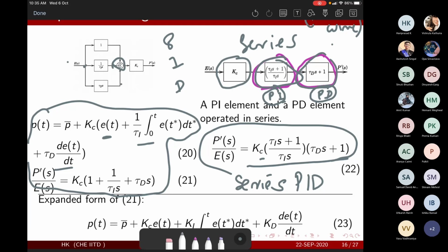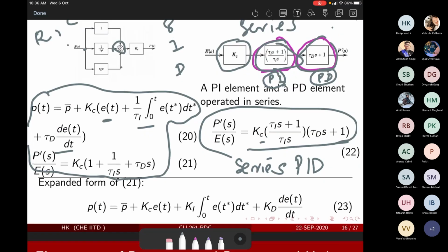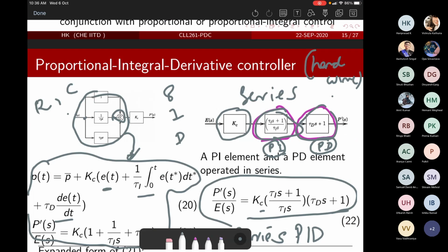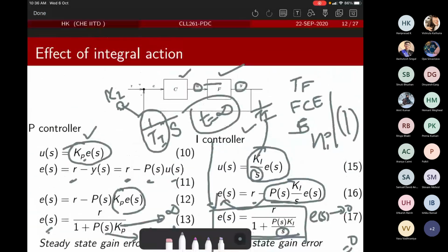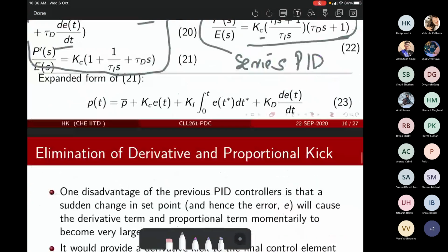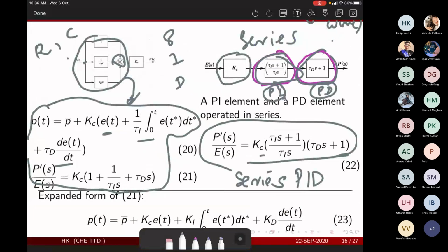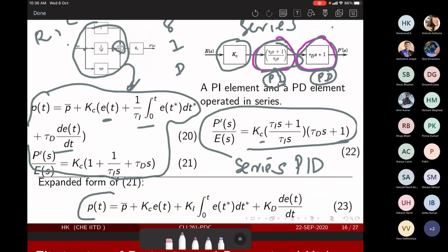So again, these are hardware implementations. There is nothing you could do because you have a resistance, a capacitance, a source and wire; this much you could do in reality. But despite the fact that there are multiple tappings and multiple joinings, this form is very close to the theoretical PID controller structure. So this is what would be most widely used everywhere, the parallel form of PID.